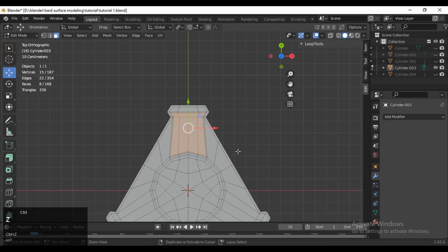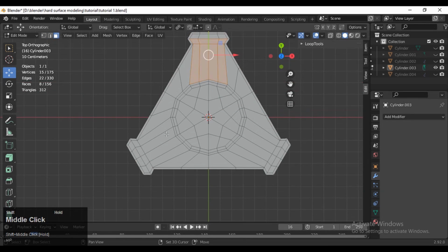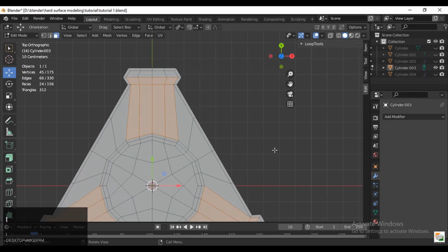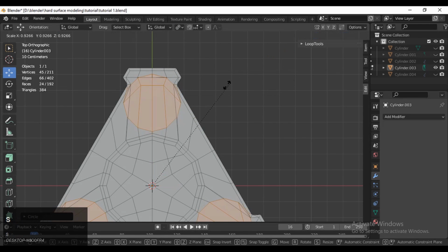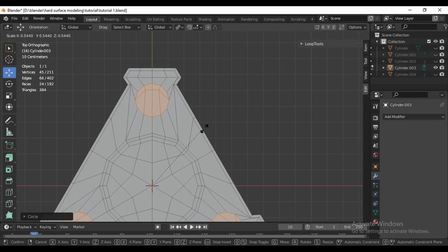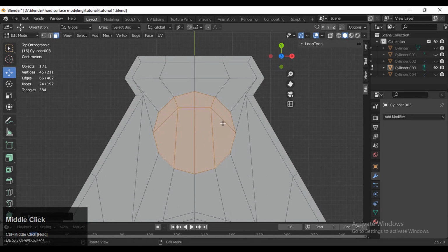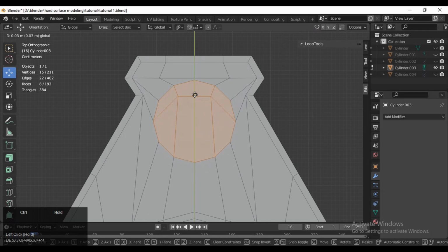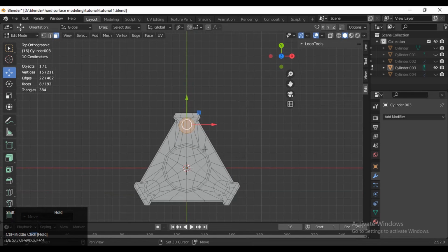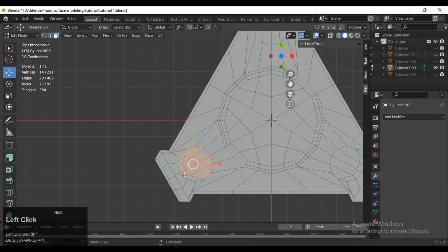And you can see I'm repeating that process one more time because I didn't select these faces. So just select these faces and do the same step one at a time for all these faces, and then insert and then use the loop tool and make sure individual origin is on, which is the option beside the magnet. Just turn on that option, and then you can scale them like this. And then you need to move these circles.